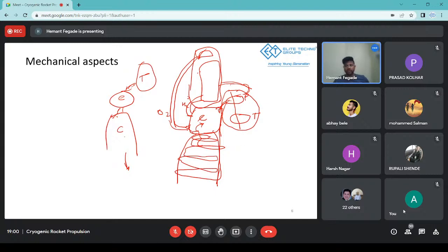The basic concept is that a pump is needed to regulate the flow. Then your hydrogen needs to expand. It needs to gain temperature. It needs to be transformed into its gaseous form without losing the pressure that it has, because once you combust that high pressure, high temperature fuel, you will get a high amount of thrust. To raise the temperature, this chamber is very hot. This chamber can generate up to 3000 degrees Celsius, which again could cause material damage, so you will need costlier components.